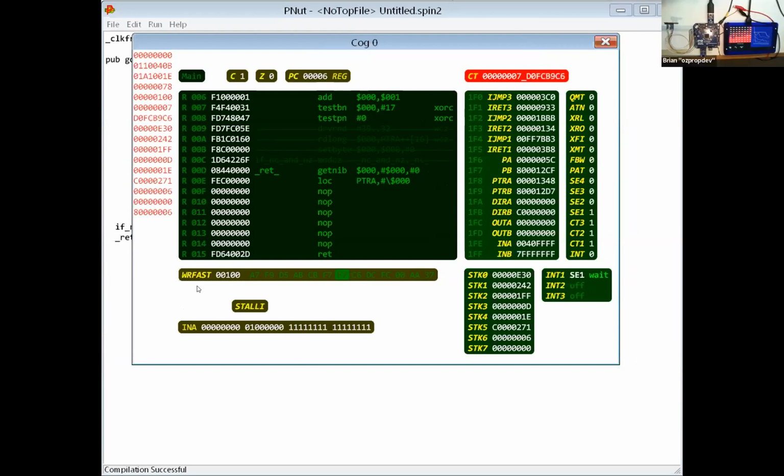Yeah, that's showing the internal pointer for the FIFO reads. Is that right? Or writes? Yeah, so it means that you have read fast versus write fast, right? Yeah. You're always in one or the other because the FIFO is always alive, but it may not have to do anything. But so this says you're in write fast mode.